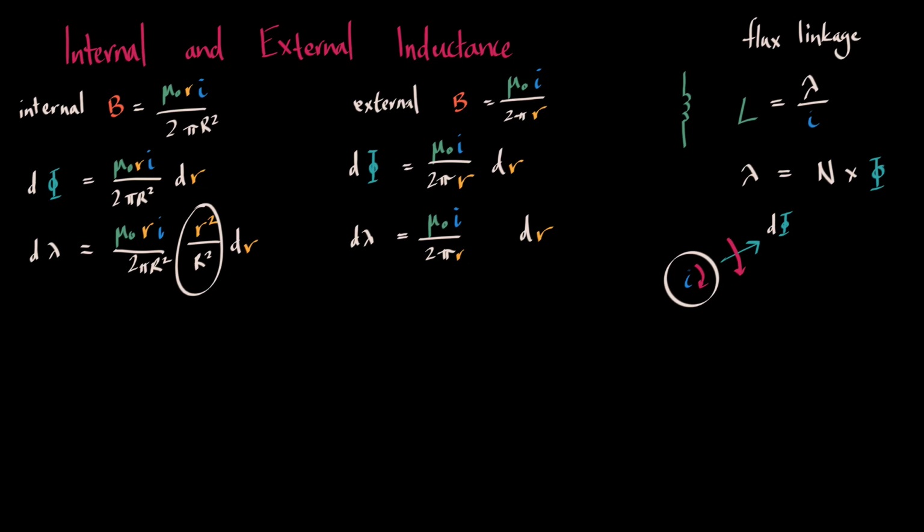To determine our flux linkage proper, we will need to integrate over a distance d. For a single wire, this should be an infinite integral. In a two-wire system, however, we select d to be the distance to the return path, another wire of opposing current flow. Here we are assuming the radiuses of these wires to be the same. We can now begin to consider the two-wire system in more detail.